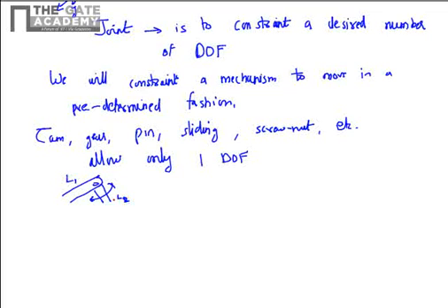There can't be any translation of link 2 with respect to link 1. There can't be any movement in the other planes of rotation. So only one rotational plane is allowed. Similarly, in a sliding joint, only a linear degree of freedom is allowed. There can't be any rotation. So in a piston-liner arrangement, there is only 1 degree of freedom, that is translational.